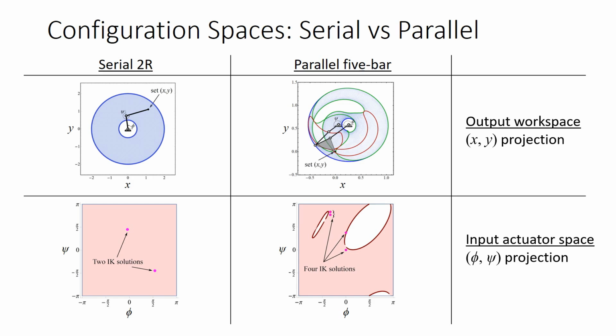the semi-axis of the velocity ellipse normal to that bound collapses, offering a reaction force in that direction in the absence of input torques. It is important to note that output singularities do not suffer from force transmission problems.